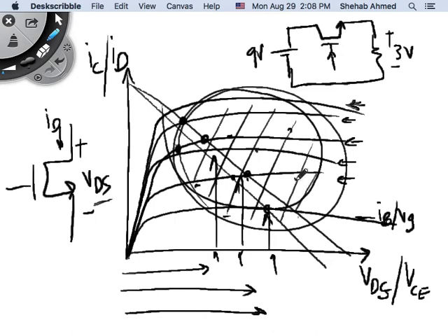When you're operating in this region, it's basically creating a relationship between voltage across the device and current through the device. So you're creating a relationship between voltage and current. If this relationship is linear, we have V equal to R times I, and we have Ohm's law. But in general, this relationship is not linear. You can choose any point here as your operating point, and hence control the voltage across this device to be 6 volts all the time. And hence you're creating your linear regulator that way. You can do it this way, and the problem with that, we said, is the efficiency that you lose.